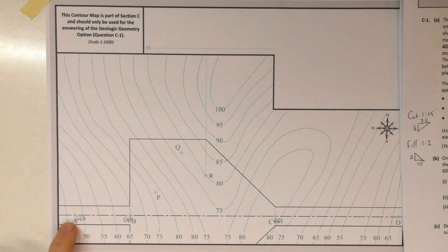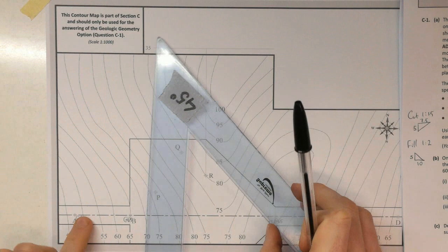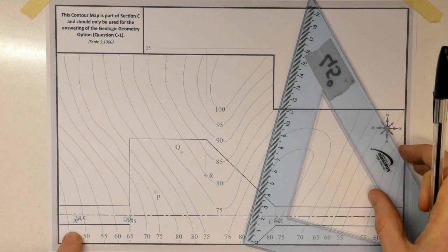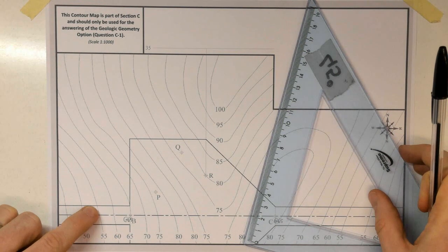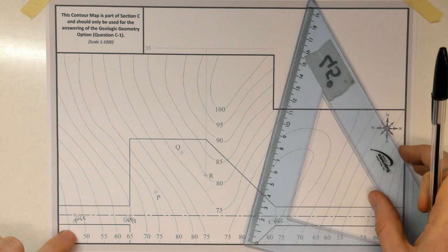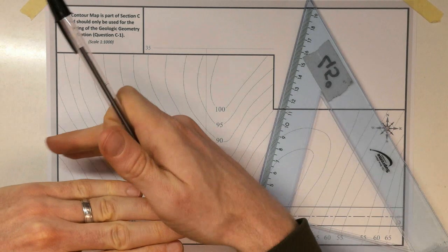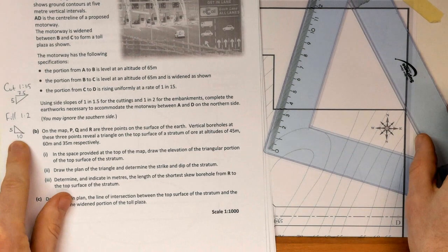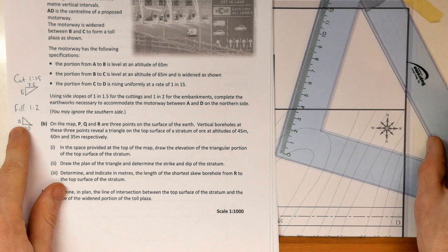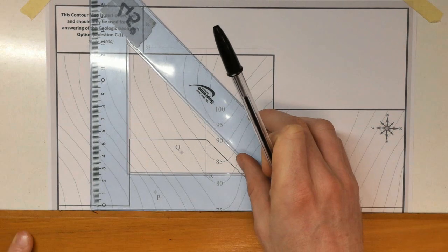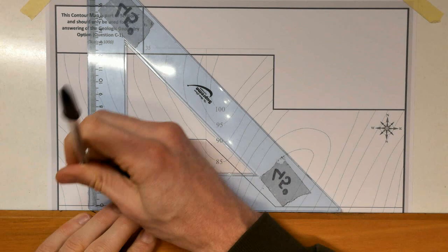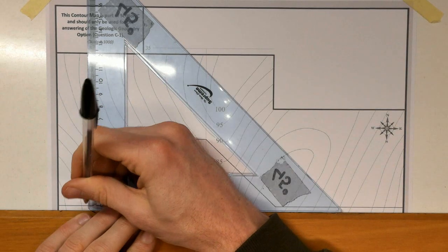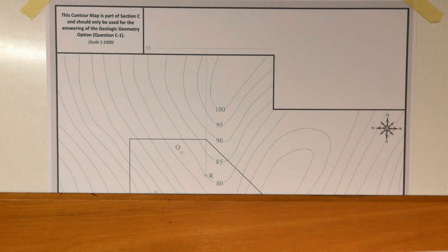We're at 65 here for A. And we can see here that all these measurements at A, we've got 50, 55, 60, so those are all underneath the level of the road. My road's here, all those are sloping down away, so I need to fill in that position. We say that our intervals there are going to be in 10mm intervals. Every 5 metres we go down, so let's go 10, 10, 10, and maybe 65, 60, 55, 50, that should be enough. So let's draw those.